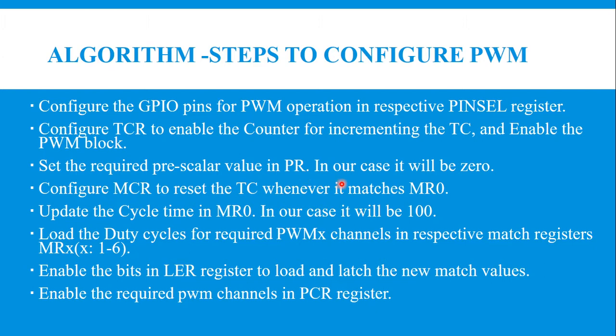Next, configure MCR. MCR is the match control register, which is used to control the resetting of TC, the timer counter, and generating an interrupt whenever a match occurs.